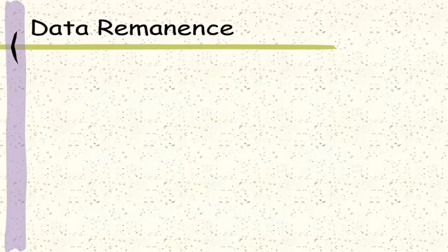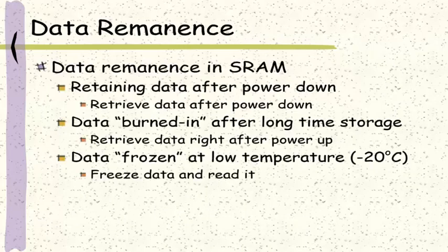When secret keys or data are stored in SRAM, they may leak in several ways because of the physical characteristics of SRAM. First, after power is down, SRAM will still retain the data for a short period of time, so the attacker can try to steal the data during this period.